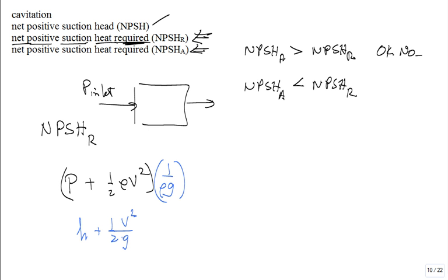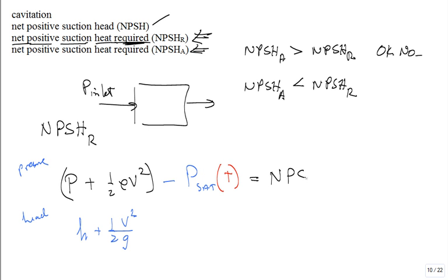And now that has to be above something. I'm going to do it both in pressure and then in head. Okay, so pressure, it has to be above the saturation pressure of the fluid. The saturation pressure of the fluid is a function of temperature. And so this equation right here is the net positive suction head in pressure.